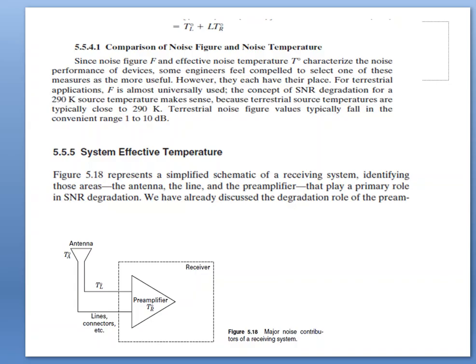The above equations describe the temperature Ts at the receiving antenna terminals. The equations describe the power received PR at the receiving antenna. These are the definitions used throughout the chapters, preferred by system design, antenna design, and thus working on the transmitter side of the link. It is most important to note that there is another set of definitions used by receiver designers, who prefer to describe the system temperature and received power at the input to the receiver.